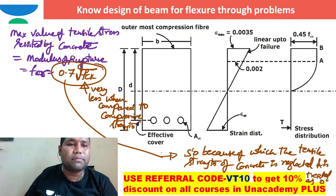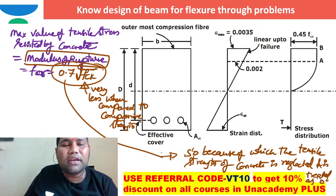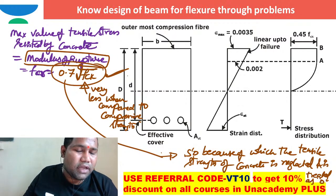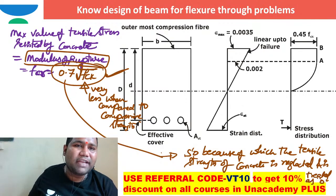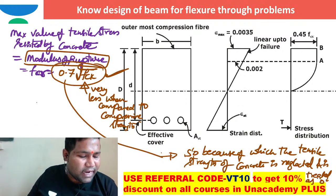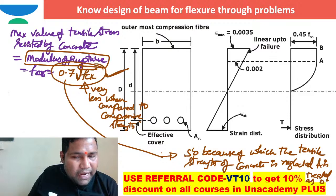Some people will also ask me, sir, how to work out this modulus of rupture in laboratory testing? This is an empirical rule. How to evaluate the modulus of rupture? If I want to work out the actual value of modulus of rupture, the flexural tensile strength of concrete, I hope you know, you take a prism of dimension 150 by 150 by 750 and apply a bending test.